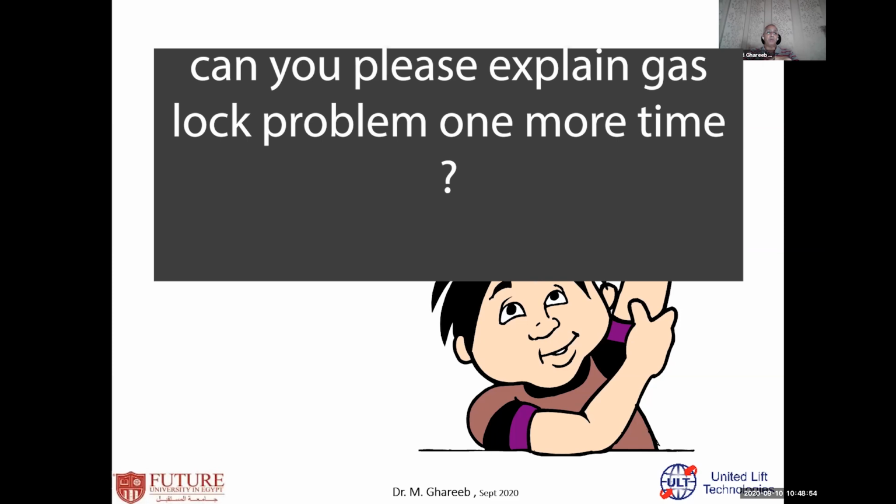Going up in the upstroke, I have a pressure I already compressed in the downstroke. Going up, yes, I decrease this pressure, but the pressure is not decreased enough to allow the standing valve to open, because below the standing valve is a low pressure, the pump intake pressure, the bottom hole flowing pressure.